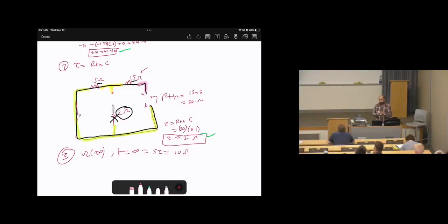That's also something important. So I'm going to redraw the circuit. It's very important that for each step, you draw an equivalent circuit. Don't solve them for only one circuit. Draw a circuit for step 1, draw a circuit for step 2, draw a circuit for step 3, because again, each step is independent of the others. The simplification that we did in step number 1 does not mean we will apply it in step number 2 or step number 3.